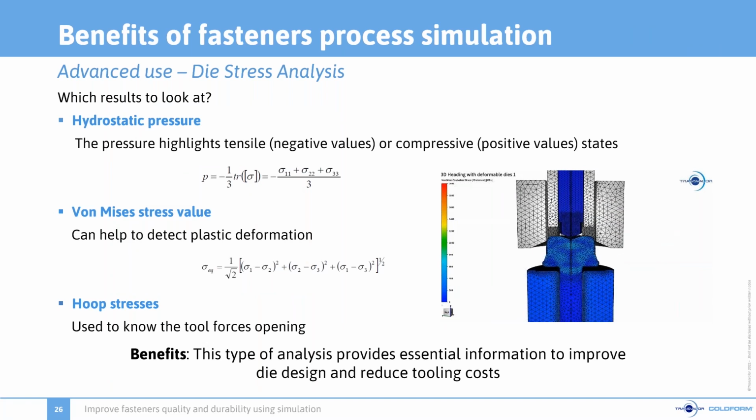Working with rigid dies is good for the analysis of the material flow, the forging load, or the properties of the part, for example. But if you are interested in having information related to the dies, such as stresses, you have to work with deformable dies.